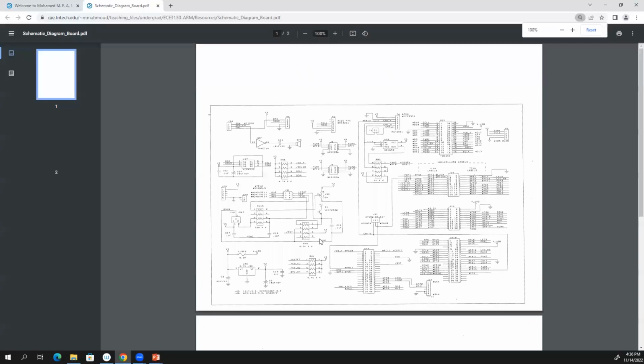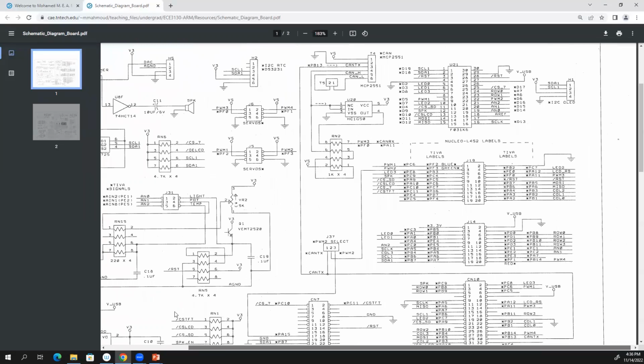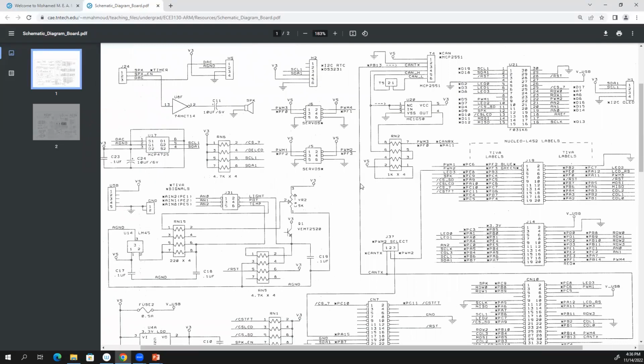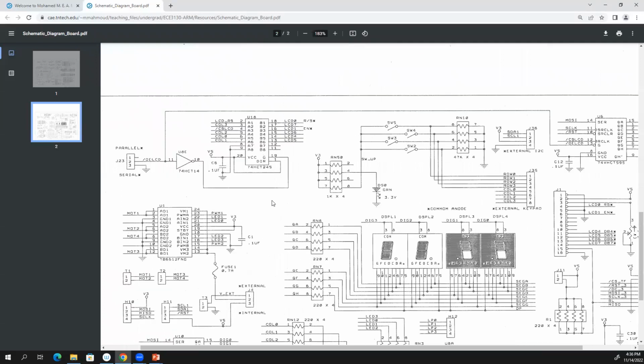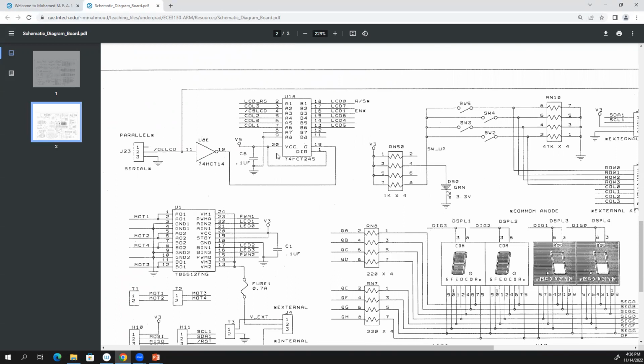Look here, guys. I want you to understand again how the people who designed this board made it, as I told you. For the LCD, I used only one chip, because every chip has eight pins. In the case of the LCD, how many did I need? As I explained before, 1, 2, 3, 4, and 2. So I needed only 6. This shift register can give you up to 8. You understand what I'm saying?